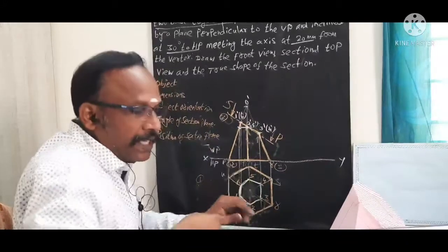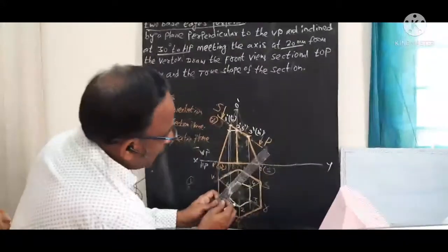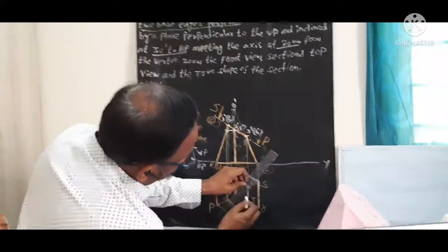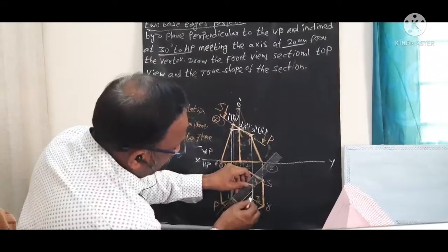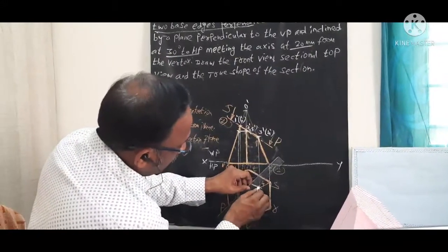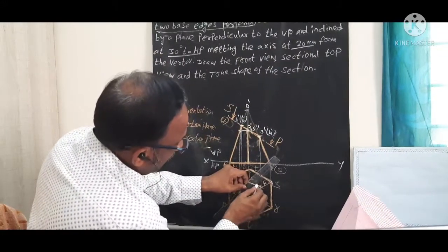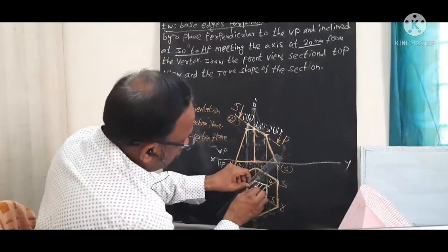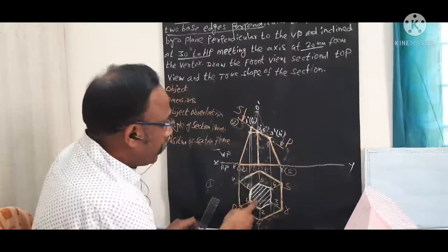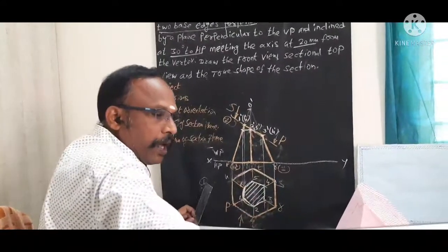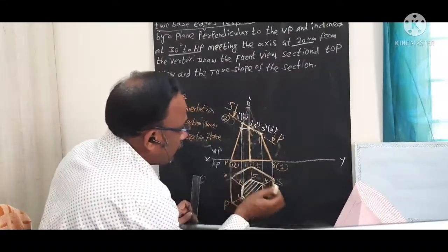Now I want to draw the hatching lines. That is the inclined line drawn as 45 degree. So first line equally spacing. You can leave some spacing, equal spacing between them. Then we can hatch like this. So this is the hatching line. Only this cut portion is visible here. So remaining thing you need to have this dark. This line is also visible.